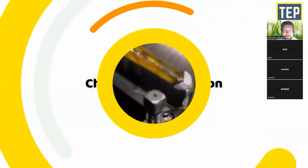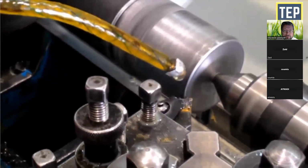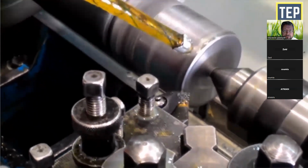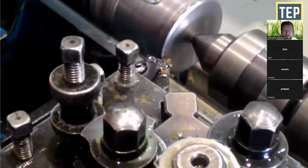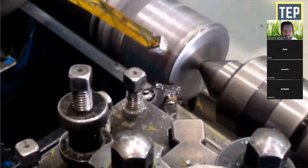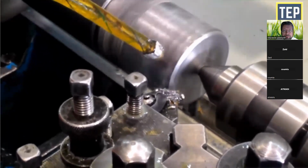Chamfering operation. It is the operation of getting a beveled surface at the edge of a cylindrical workpiece. It is done in the case of bolt ends and shaft ends. This operation helps to avoid damage to the sharp edges and protects the operator from getting hurt during other operations. Chamfering on a bolt helps to screw the nut on easily.